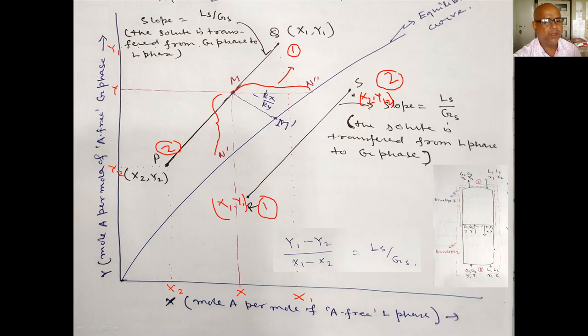Okay, so in this case, whatever the carbon dioxide content in ethanol, that will be higher. It will be much higher than your equilibrium, then only the stripping will happen. Because in this case, this will be your liquid phase driving force, and this will be your gas phase driving force, isn't it?